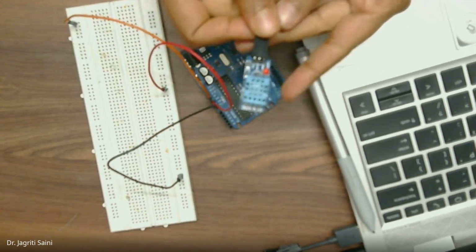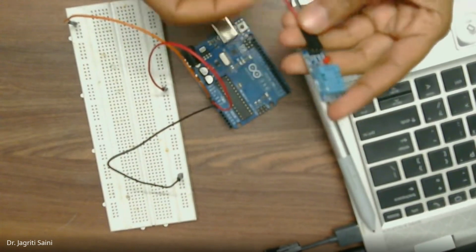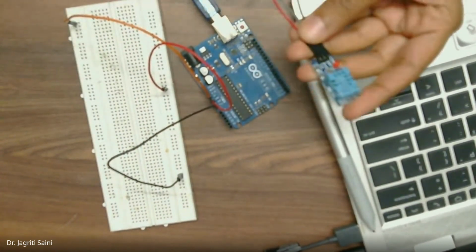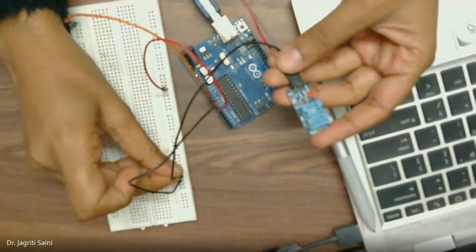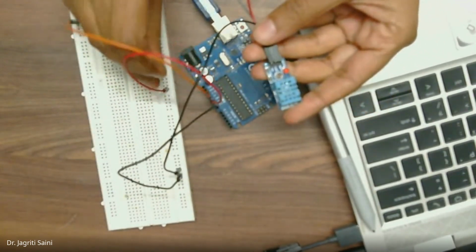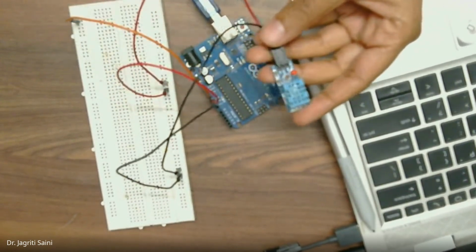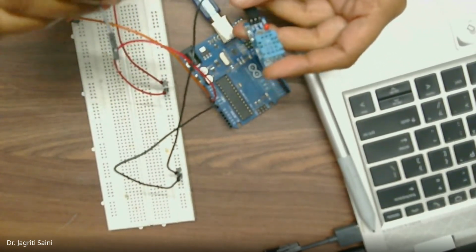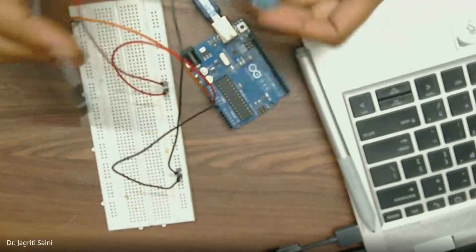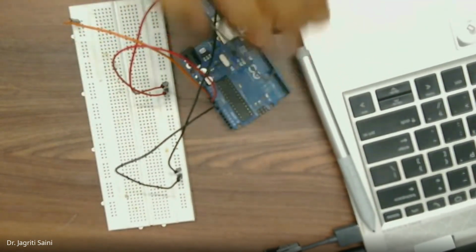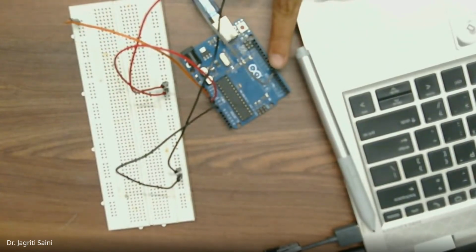Now I'm using the very first sensor, that will be my DHT sensor. I'm taking up the first wire. I'll be using ground for safety purposes. I'm inserting it right here. Then the VCC connection I'm using in the VCC section, and then this data point as defined in your hardware or your software. If you remember, we have used pin number 7 of your digital port. So accordingly, I have connected it on the digital port pin number 7.